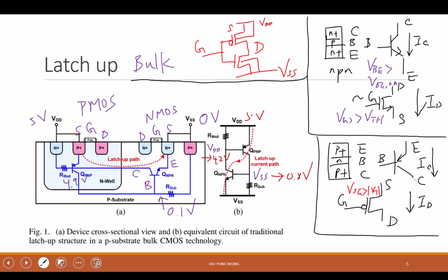But however, remember this is a parasitic one. True that if you really try to design a high gain transistor, the problem is I did not tell you all the details. In reality, we want to have a nicely doped collector next to P to avoid the so-called early effect. It's just like the channel length modulation in NMOS transistor. So when it is nicely doped, you might get freeze out.